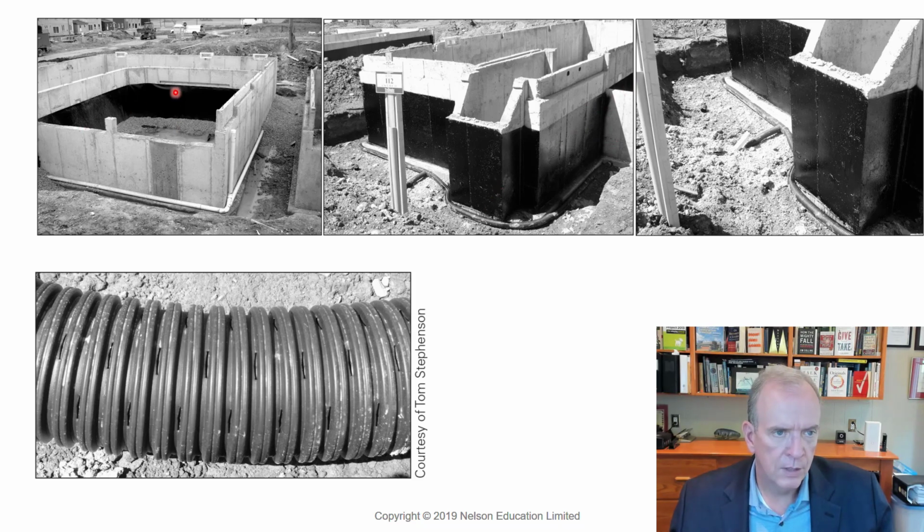And so you can sort of see around here, they've actually put a drainage layer around here. And you can sort of see there's a key in place along here, and that's when they're gonna backfill this, they're gonna compact this, they're gonna put a gravel base underneath it, and then there's this key that will tie the concrete floor into the walls so that it doesn't settle.